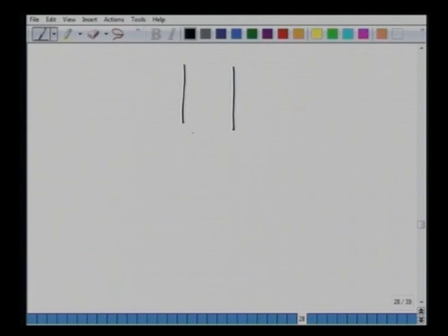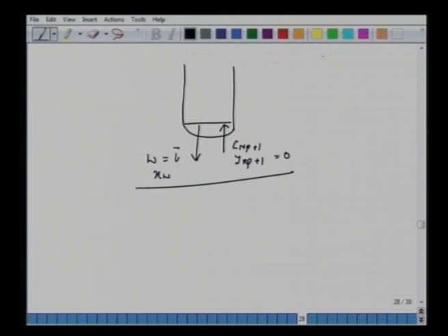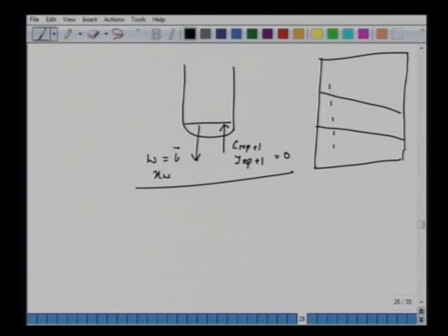So we have this bottom plate. From the bottom trace we have W, which is nothing but L bar, with composition xW, and we have this vapor which is G_{NP+1} with the composition y_{NP+1} equal to 0. It's pure steam. So the top locations in the Ponchon-Savarit method, if you redraw here, will not change. What will change here is xW. So we have to locate where this new location of xW is.